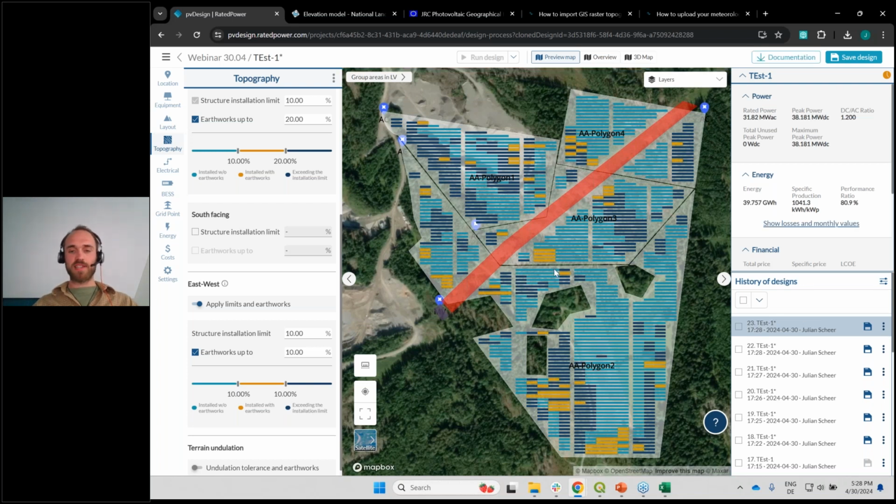And now it probably shows me what I was expecting. Yeah. So it now highlights all the areas where earthworks are possible, up to 20% slope. So this 20% now means that all these areas were higher than 10%. That was my initial analysis, and up to 20%. So this is the range in which I'm currently calculating earthworks, because it might just not make sense to go higher, because 30, 40%, that's just too steep to calculate earthworks. So that's why I just went with 20% in this example.